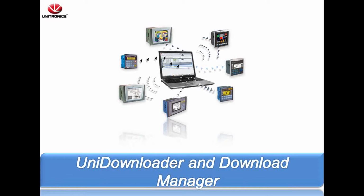Using Unitronics Downloading Utilities enables you to build a complete compiled project and send it anywhere to be installed in a PLC using a standalone downloader. This includes Vision, M90, 91, and Jazz controllers. You'll be generating a compressed and compiled application from within either U90 Ladder or VisiLogic directly. Your end user will be able to download the application and OS, but will not be able to view or modify the application or logic in U90 or VisiLogic.